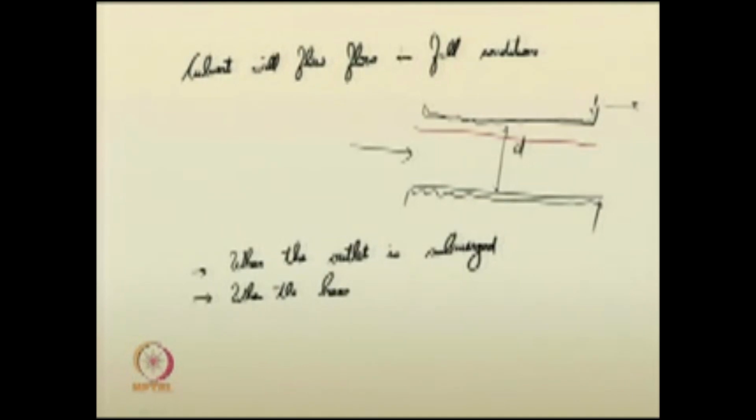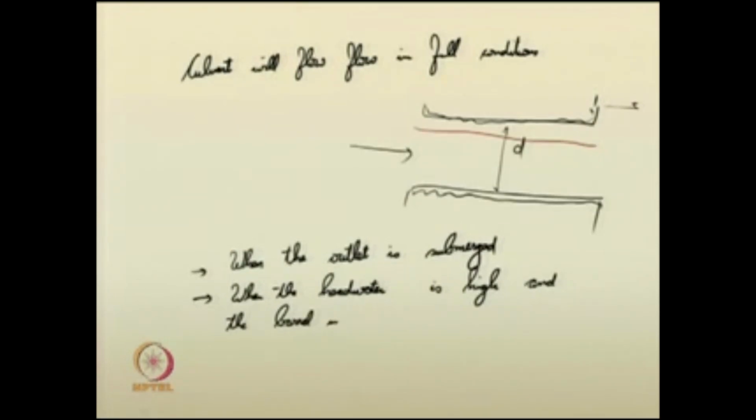Or when the headwater, the inlet water condition, is high and the barrel is long, you may have full water condition. So, if the water at the inlet is much higher, then it may flow fully. These conditions suggest that the culverts may flow in a full situation.